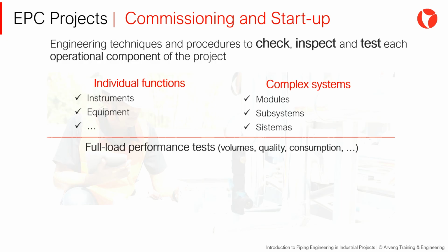Either immediately after startup or just before the end of the warranty period, it is common to carry out a performance test at full load. The objective is to demonstrate the guaranteed production volumes, quality, and specific consumption of materials and energy. Verification of whether the contractual figures are actually met is usually carried out by an independent third party, and it is not only relevant for owners and contractors, but also for operators, investors, and direct clients. Results are used to determine the actual return on investment and to establish contractual penalties or rewards.